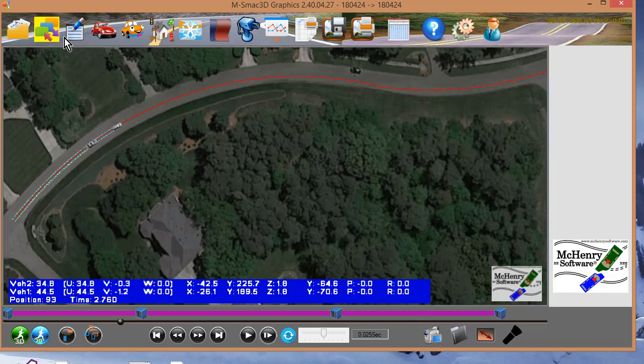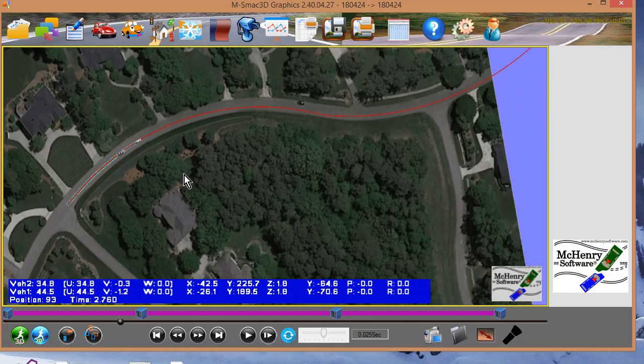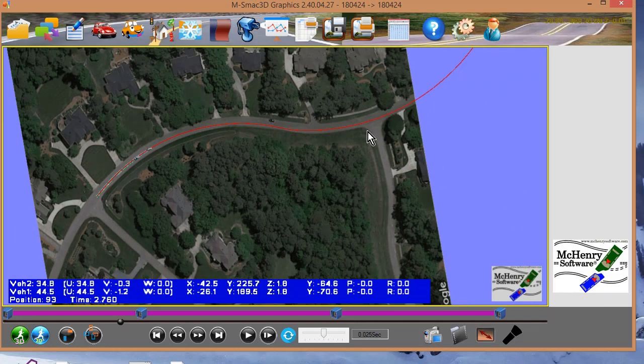First item you would do is grid, but before we do that, what we're going to talk about is we went and got this scene, as you can see, a scene with a curving road. You could have brought in the elevation. This is 3D or 2D. I'm going to run these in 2D because it's just faster. And even when you're in 3D, I recommend that when you're doing path followers, run it in 2D until you get the path looking pretty good, then go 3D, because it's only maybe 30 seconds or a minute more, but why waste a minute waiting on a simulation when results are going to be similar.